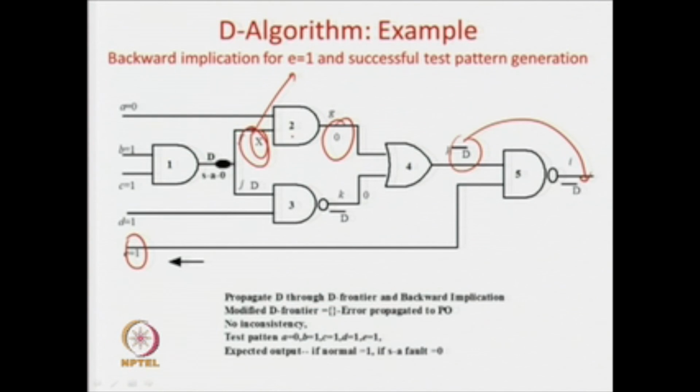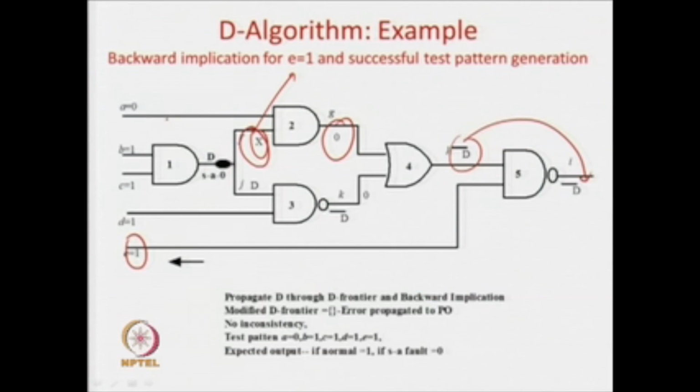Now, the other option we have: instead of the option x0, which created an inconsistency again, we tried the other option. Whenever there is a conflict, we go back to the last option where we had made a mistake. The last option that was wrong was taking x0, which was creating the problem, so there we stopped. Now we reverted it back and we are saying that we will apply 0x. Now 0x says that the whole solution has been done, because we require output 0 over here to solve the problem, and this x here stands for saying that whatever may be the case, d prime, 0, 1, the output here is not dependent on this one.